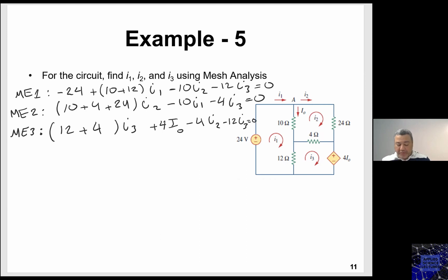Yes, it is extremely important to keep in mind how many components you have shared. Later on, this will let you verify if you have missed anything. Like mesh number 3, the one that Peter just did, he kept in mind that he has this one shared and this one shared, and two components that I3 is going through, and one voltage source.